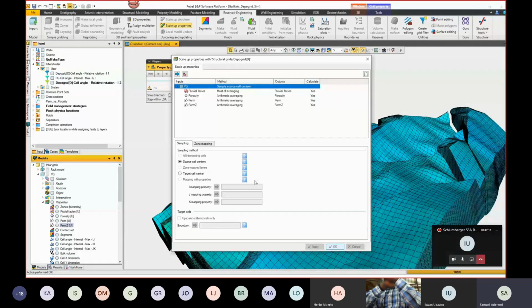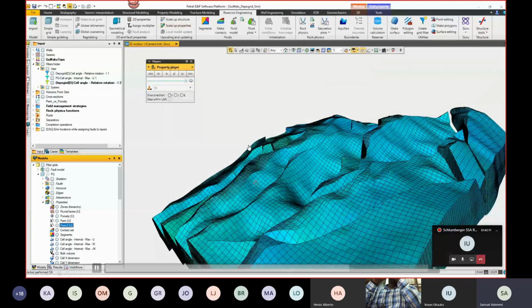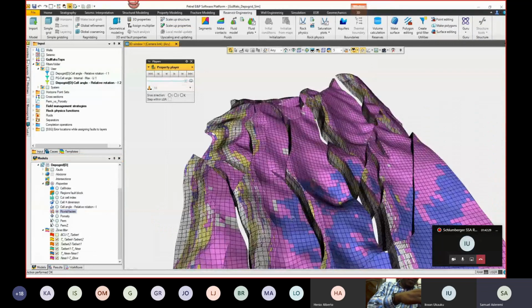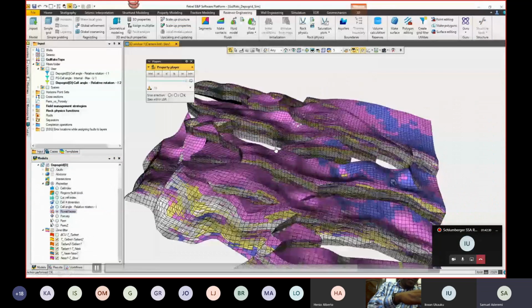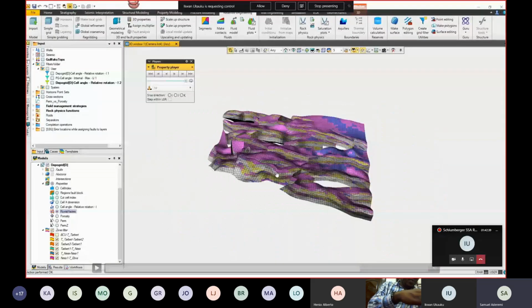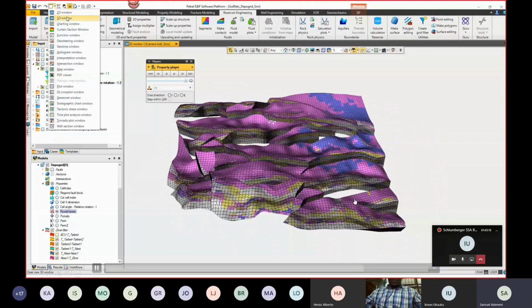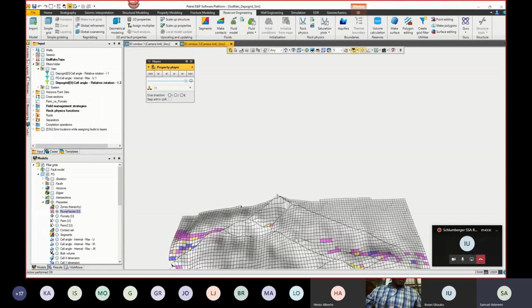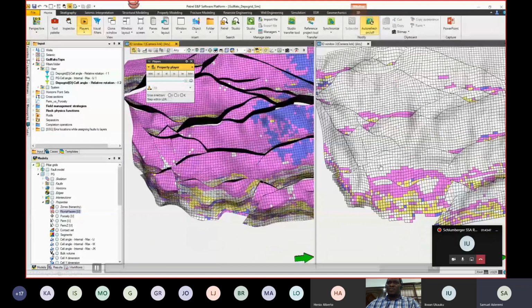And one thing that I want to point out here is you can also use the calculator the same way we usually use the calculator, right? It's the same grid. I mean, of course, you can see those properties. And there is something very interesting here. Look at the outcrop, if you display the fluvial facies, you can really see, which is really powerful. If you put this side by side with the pillar grid one, let's link the two screens together so you can see more geological details.